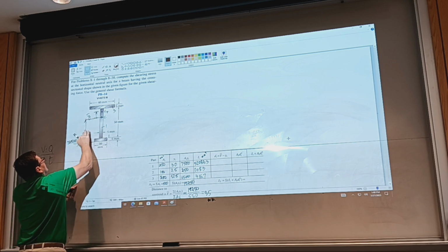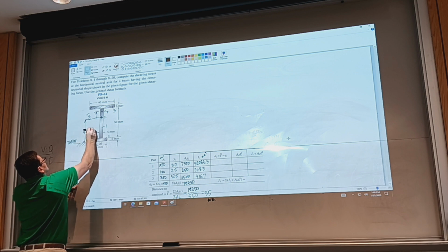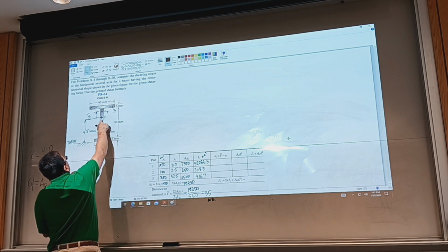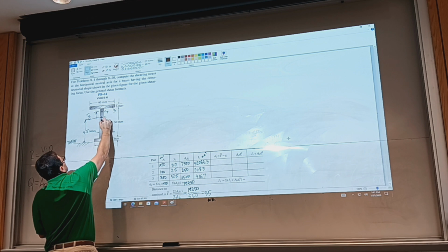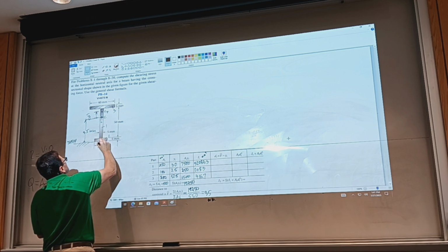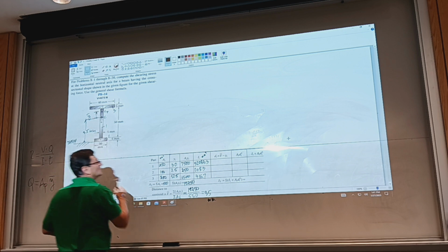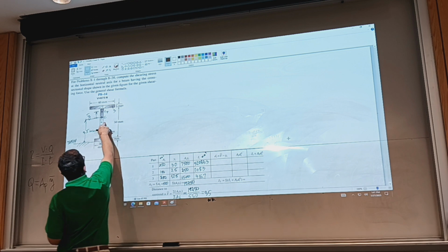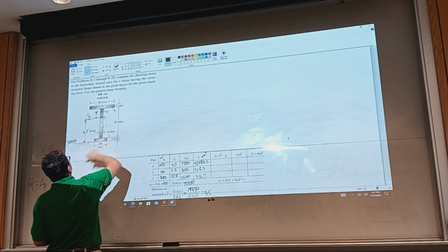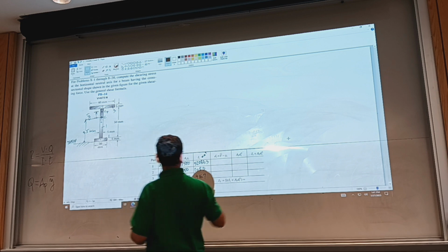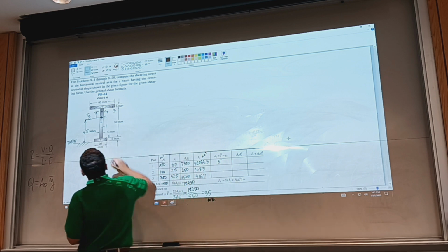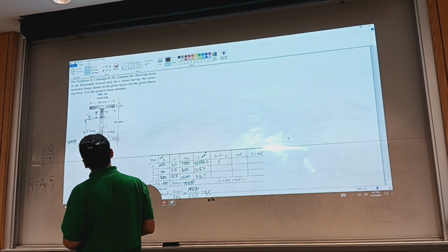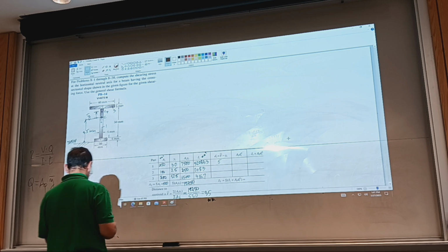Again, this is 35 millimeters, and now moving back to the centroid of the individual pieces to get the d's. So the distance from the centroid of the assembly to the centroid of just the vertical rectangle will be 35 minus 30, that's 5. The distance to the centroid of the first piece is 35 minus 2.5. So that's 32.5.